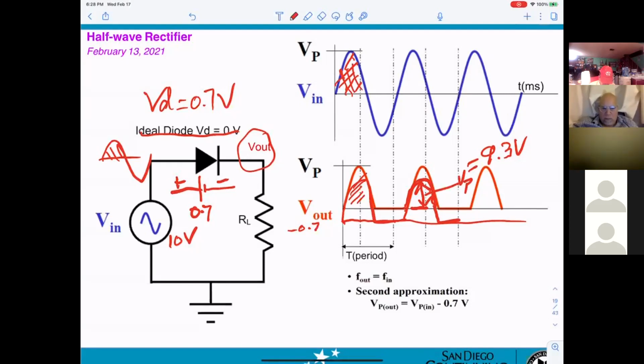When it's on, you substitute by the battery, positive, negative, value 0.7. Then I know for sure at the output here, you get two signals. One will be sideways here. Another one will be minus 0.7. So that's why first thing I draw is a minus 0.7.